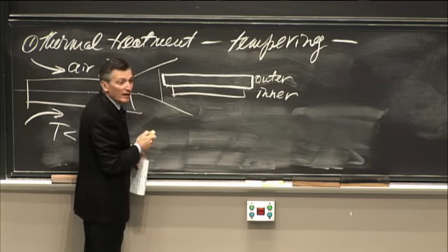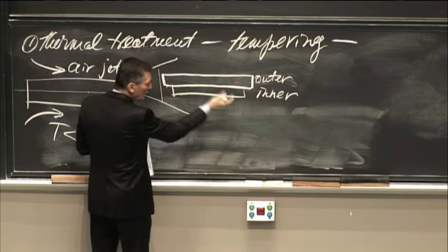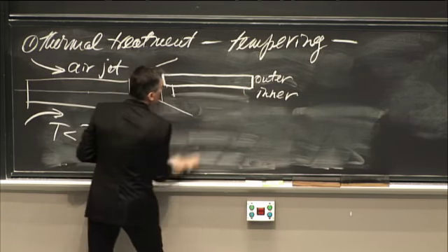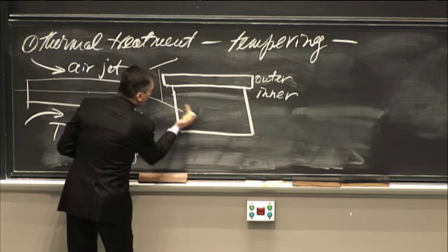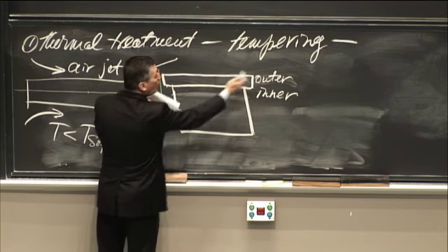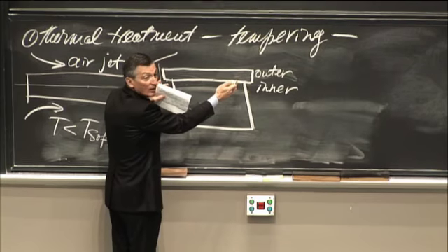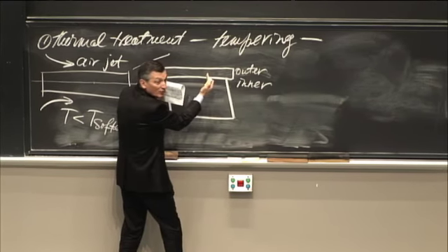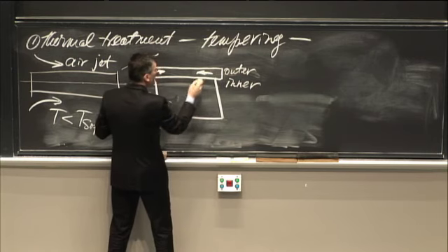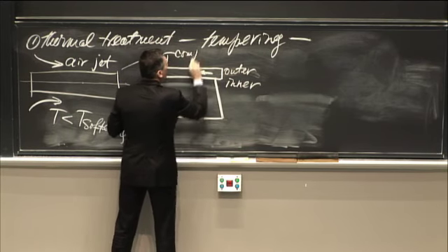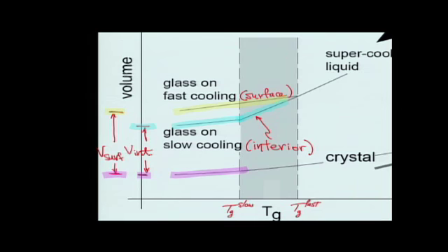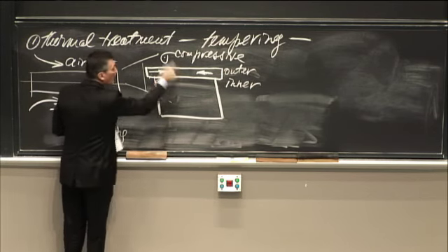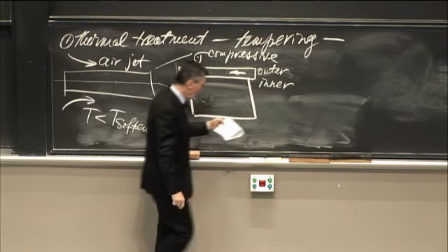And how can it have a flat edge? Because the bottom here, this is not to scale. Let's make it more to scale. The top is a narrow zone, and the bottom is a big, thick zone, isn't it? So this big, thick zone, which has a small volume, is going to pull on the thin upper zone, which has a large volume, and pull it in. Can you see that? And it's going to cause the introduction of compressive stresses. So we got to compressive stresses simply using that graph and a little bit of air. So you take that graph, put in differential cooling, and now you've introduced compressive stress. And that's all tempered glass is.